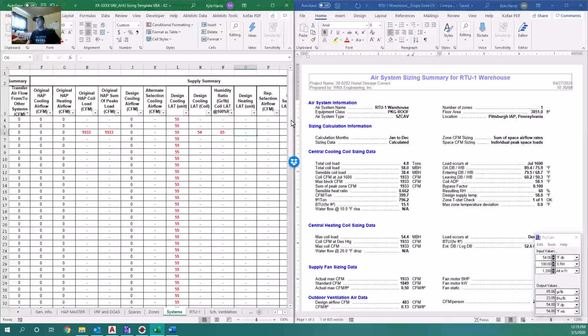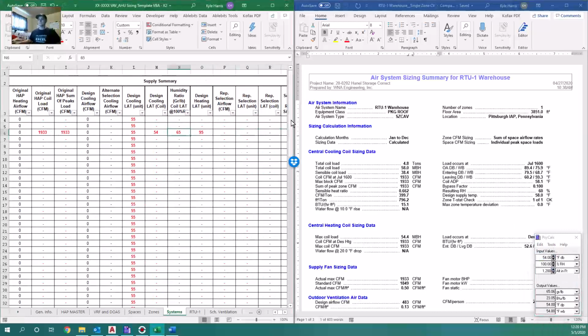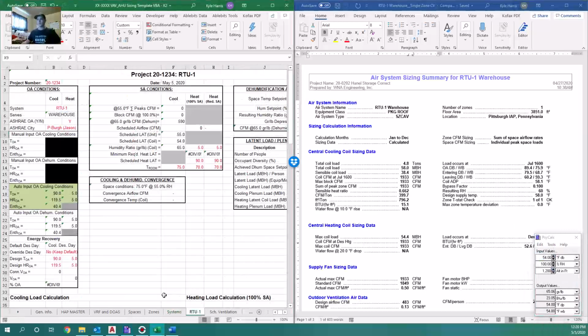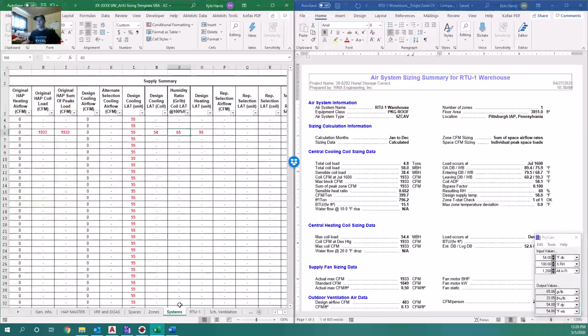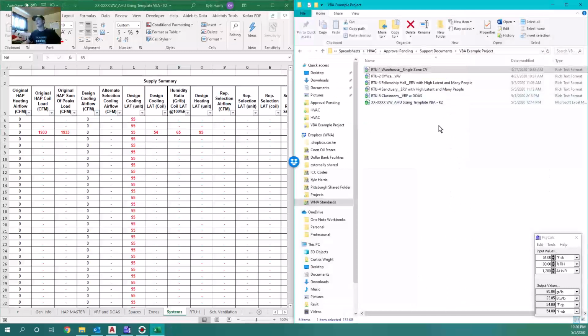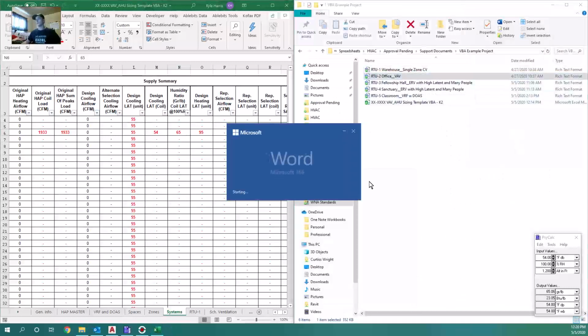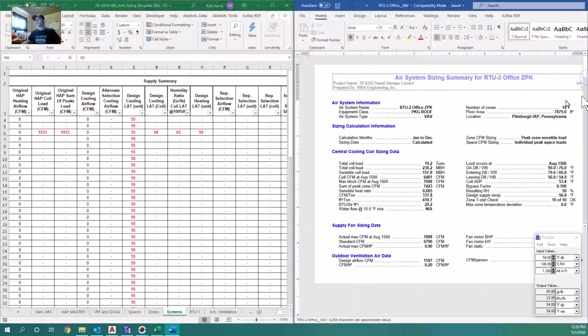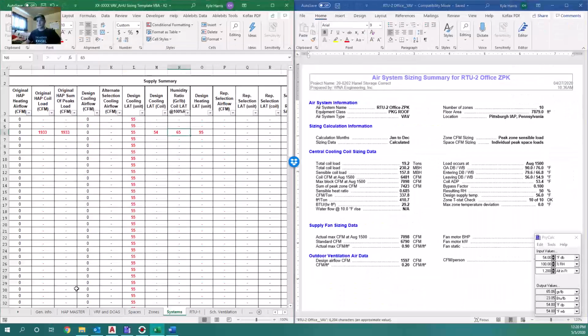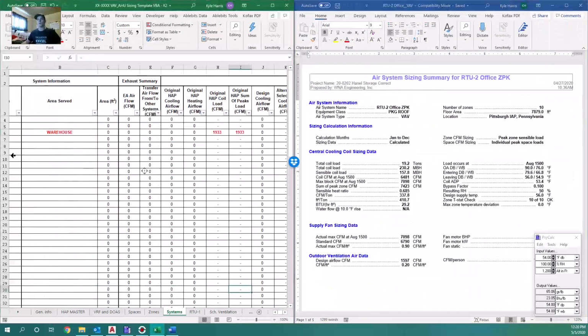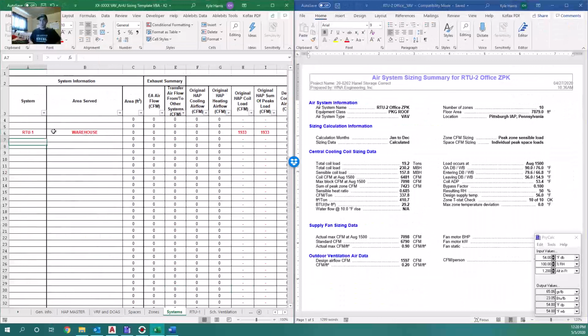And the heating, this is not a VAV system, so we're going to say 95 degrees out of the unit. And we'll see where that leaves us. So now we're done with this. We're going to close that tab and then go to the next report that HAP generated. I'm going to pull that over to the right.